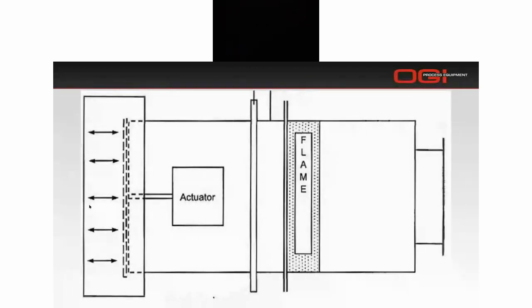Where you see the word flame, that's a flame cell element. That's this spiral wound cylindrical shaped flame element, and its purpose is to allow air to be drawn in for combustion support, but prevent flame from propagating outside of this flame arrestor to your station. And essentially the flame arrestor is what separates your general wiring inside of the flame arrestor from the class 1 div 2 area outside of the flame arrestor.